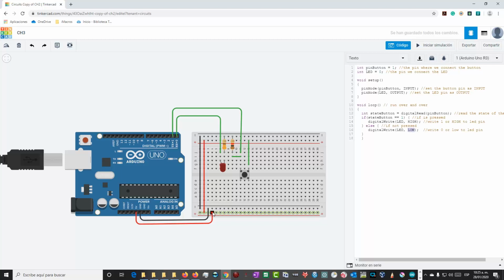So if I connect 5 volts to this, I'm going to be able to get 5 volts in this and this and this and this. And also because I am using this red wire to connect this with this, now I have also 5 volts in all of this. So the same goes for the ground. The ground is the reference, the 0 volts. So I connect this ground to here, to the minus line, and again I have ground or 0 volts on all these holes, and the same with this wire, I have 0 volts or ground in all of this.